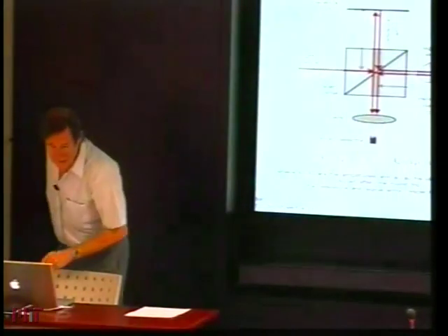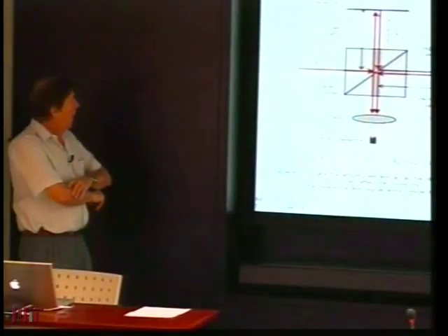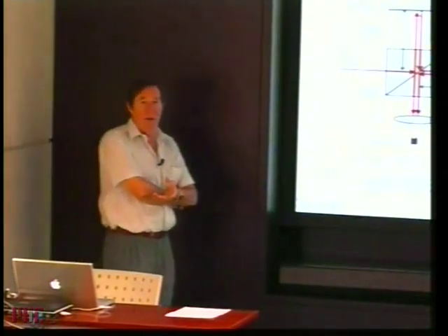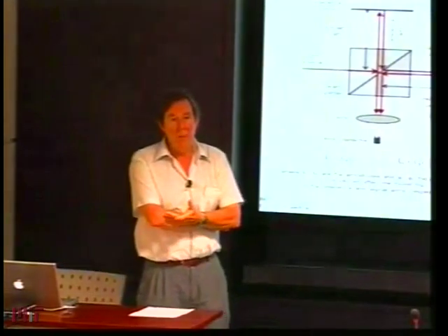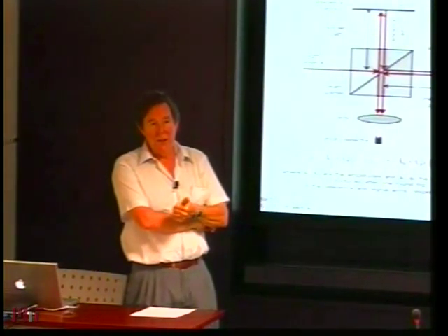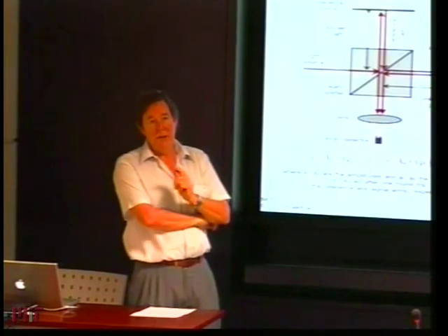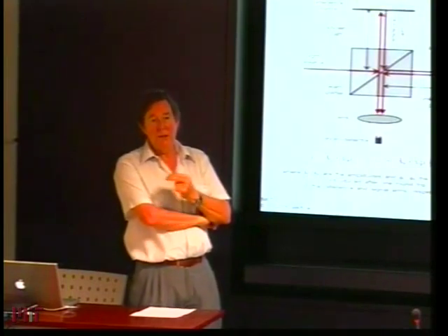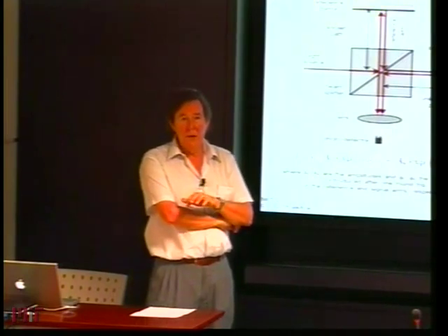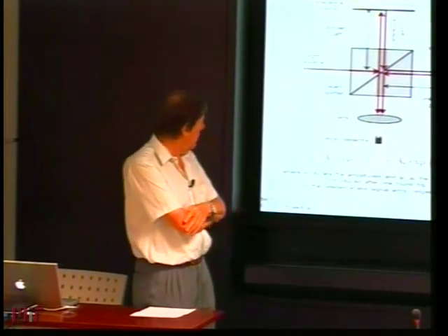And so, example, measuring distance. We've said that effectively what we're doing is measuring the optical path. So optical path depends on a few things, doesn't it? Optical path depends on the distance, it depends on the wavelength, and it depends on the refractive index. So these are all things that you can measure using this sort of system.